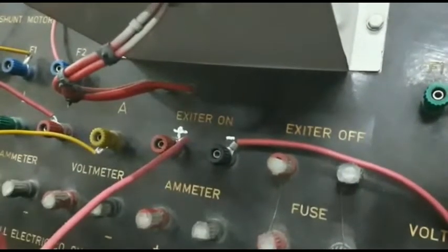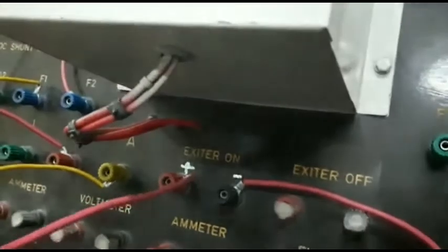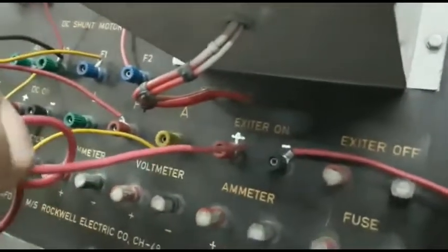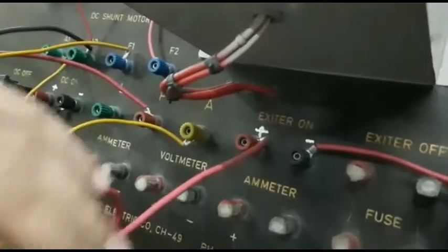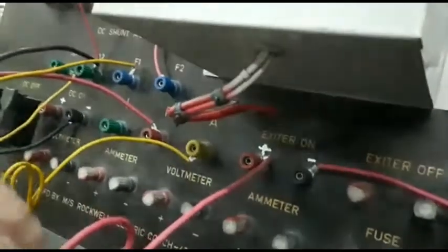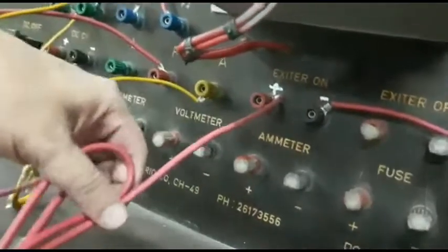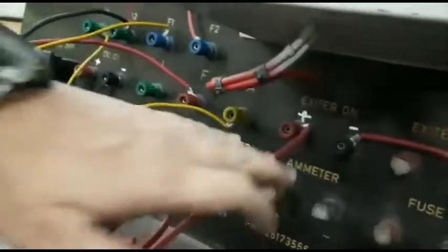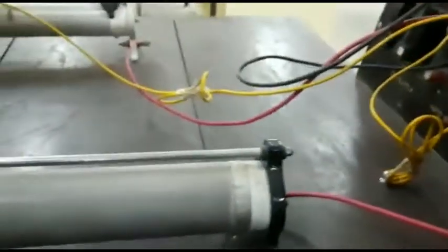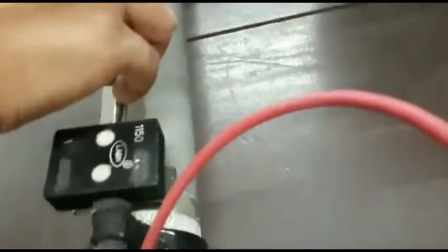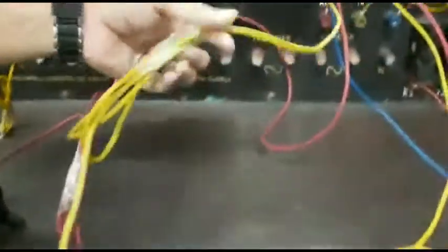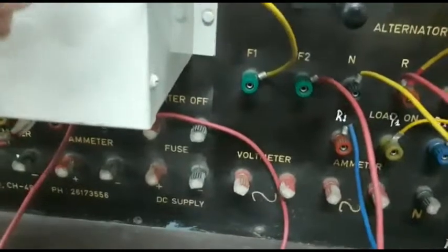Now you can see here the exciter positive is there. In an alternator, the field winding section is also having a rheostat. That rheostat positive should be from the positive terminal of the exciter, it is going to the rheostat. Okay, and the variable part of the rheostat is given to an ammeter which is connected in series. That means that the ammeter and the rheostat are connected in series. And from the ammeter, the negative part, it is going to the F1 section.